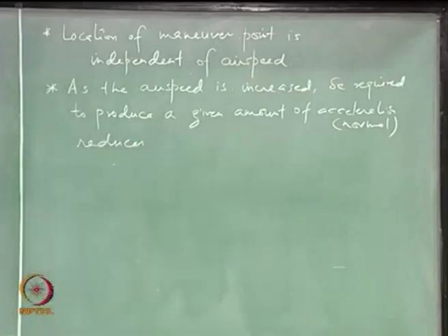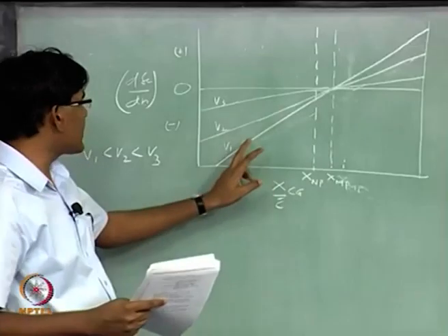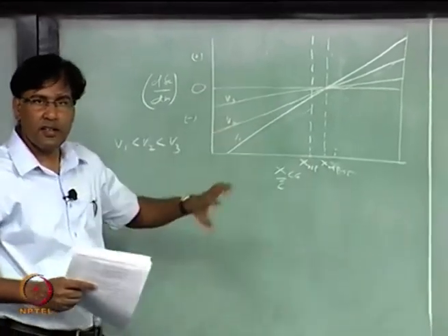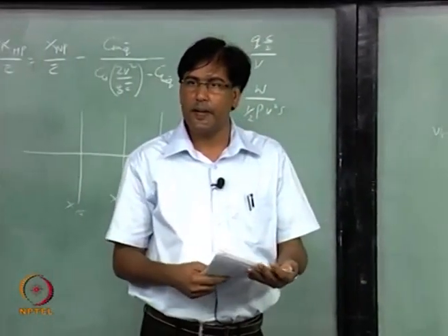Right. As the airspeed is increased for a fixed CG location, you can see that the elevator required has reduced, right.